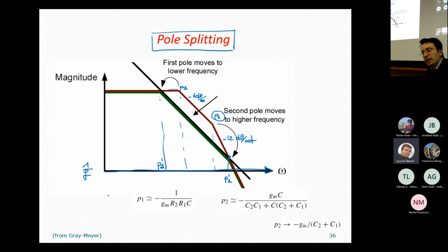And the overdrive is given by this expression when the transistors are in saturation. So this means that the square root of twice the current of transistor 4 divided by beta prime p times the form factor of transistor 4 should be equal to the square root of twice the current flowing in transistor 6 divided by beta prime p times the form factor of transistor 6.